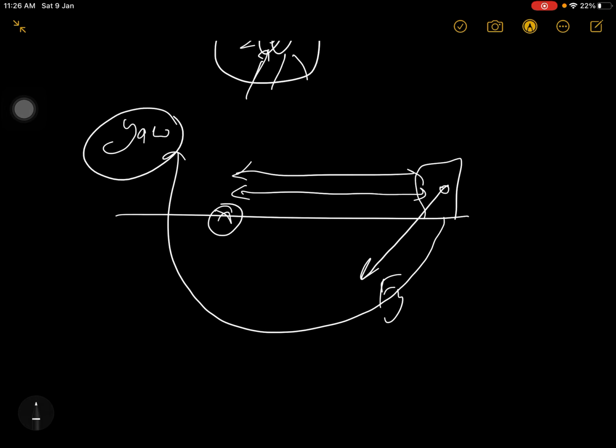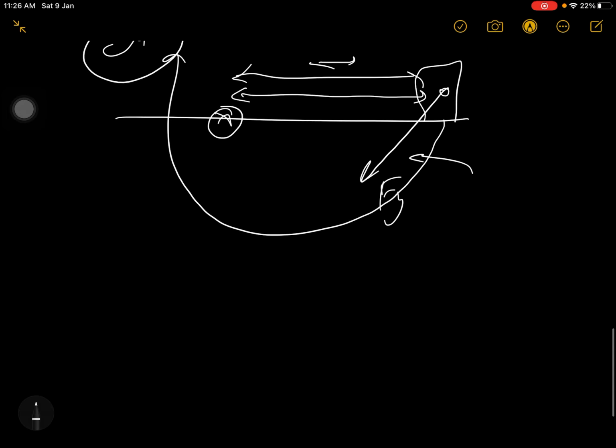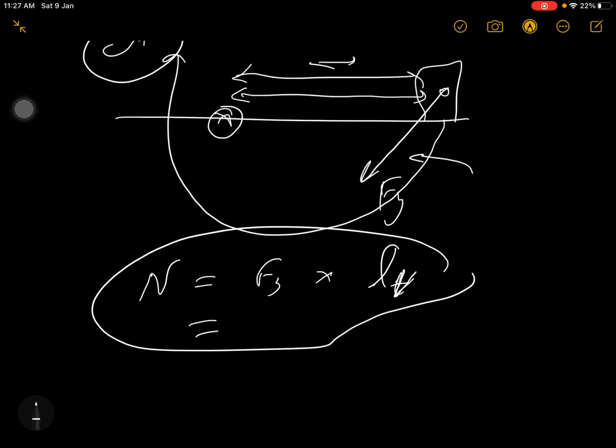What kind of moment will it be? Yaw. In aviation we call this moment yaw, correct? So multiply this distance with the force, and you get the moment, and the symbol we give is N. So N is equal to Fy into what we call the arm length, Lt. But if you are using the vertical tail, then you can put the symbol Lv, correct? That's all. We got the answer. Multiply all the terms given in the question.